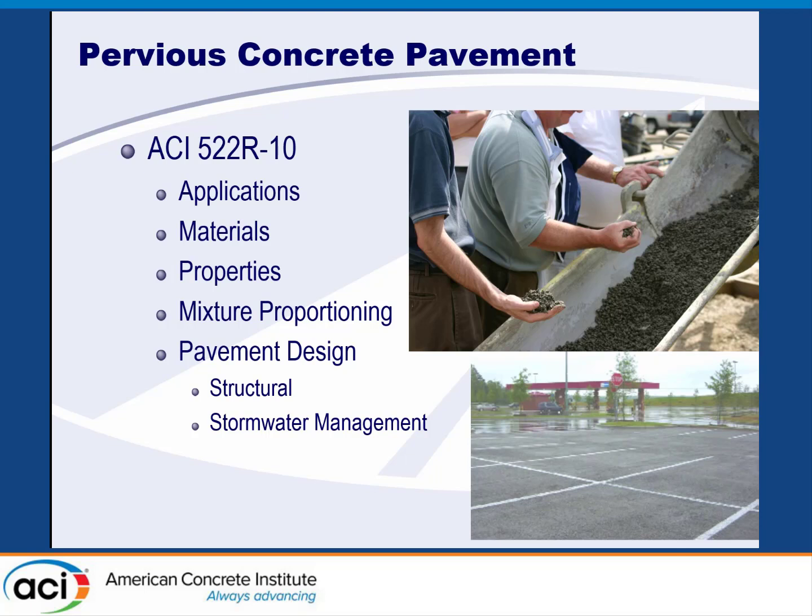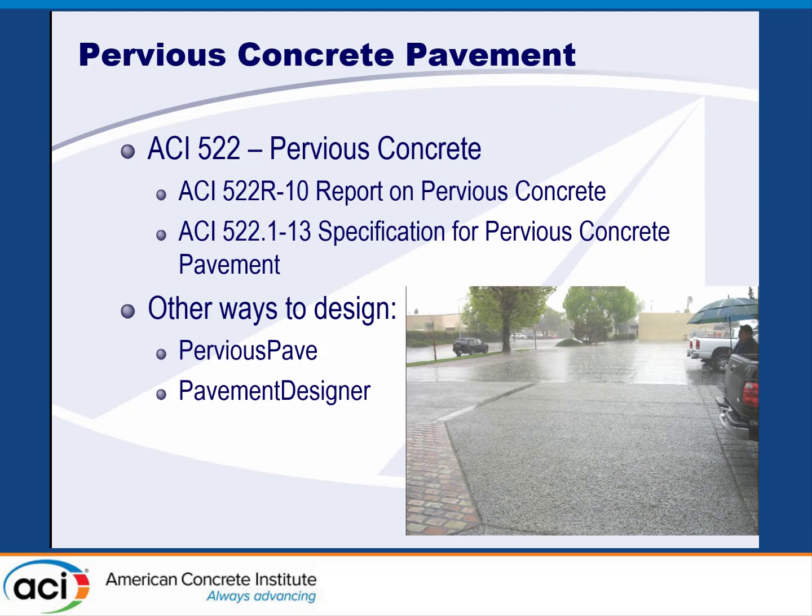And so it also goes through the pavement design. The structural design is very similar to our streets and local roads, as well as our RCC design. The big difference here is you also have to consider a stormwater management design. So we're not just talking about carrying the load, we're talking also about storing the water. And so that's the big benefit of the 522R10 guide, is that it covers that stormwater management. It's also covered within the PerviousPave tool that's available as well.